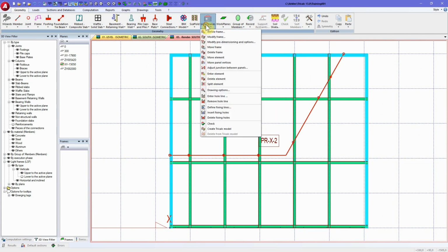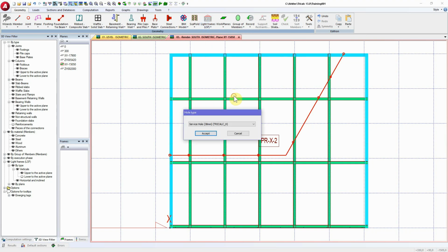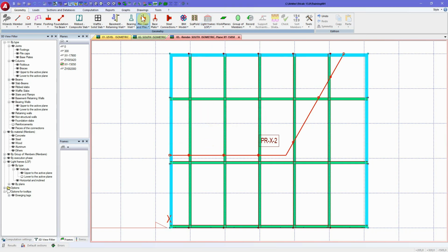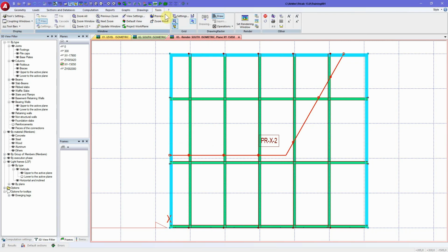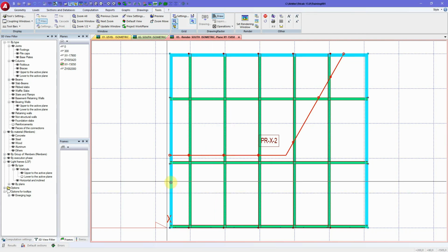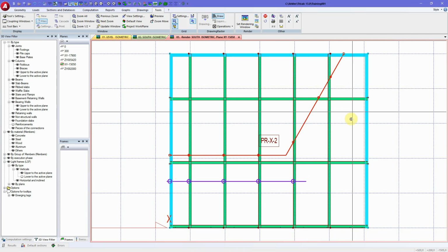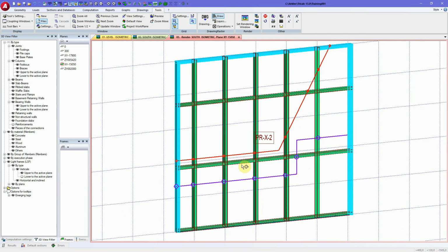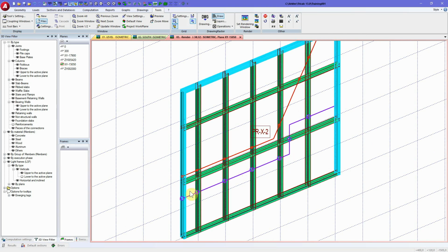the holes inserted. Also, you can insert here a CAD drawing in this vertical plane and use it as reference for creating your holes also. Enter the hole line. If I change the tool, for instance, I'm going to set it, and I'm also going to change the rules here of the grid line. So here in the settings, I'm going to set my mouse to create alignments in multiples of 20 centimeters. So when I'm going to create here a new line, it will always have 20 centimeters reference distance between two lines. So it is nice to separate columns or separate lines, hole lines with that reference.